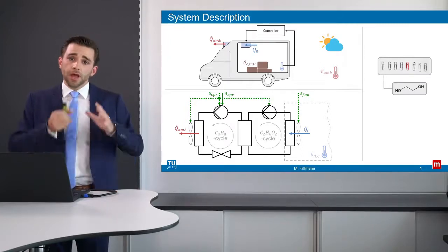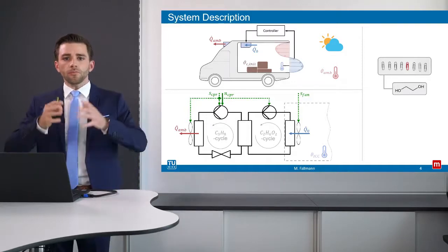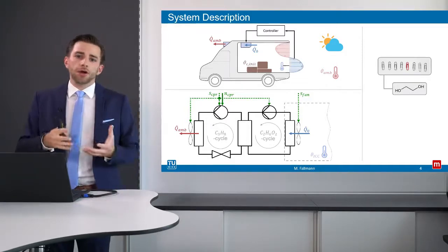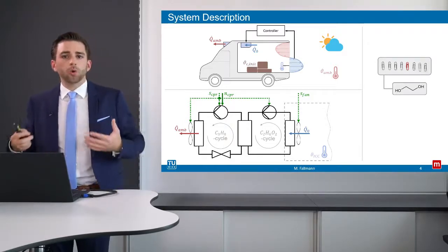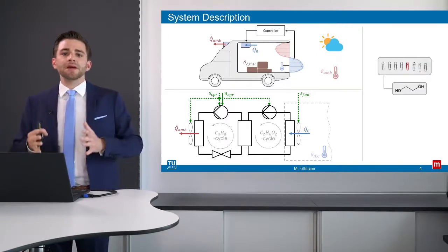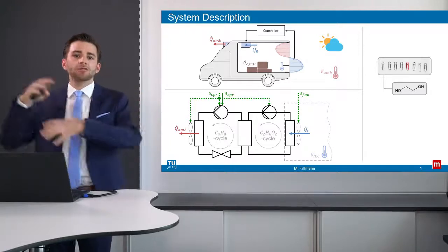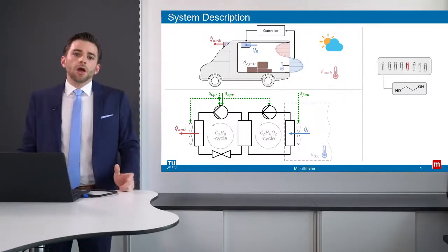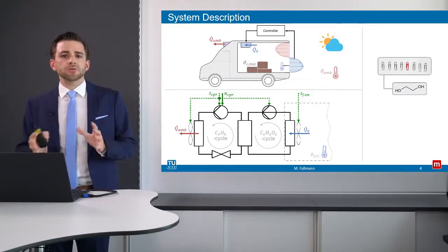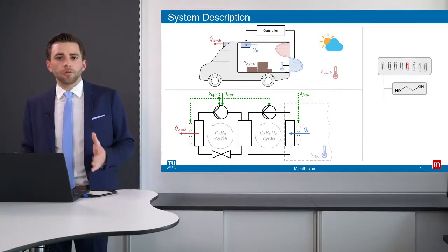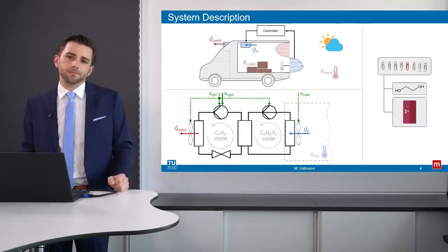But however, door openings have the most significant impact on the inner air temperature. Despite that, most of the current control approaches only cover them heuristically. We, by contrast, incorporate them in an explicit manner and model them as an actual connection between the cooling chamber and the ambient air. This is of course the second special feature of our model and allows us to better cover given circumstances, but of course introduces an additional binary variable, the door opening.